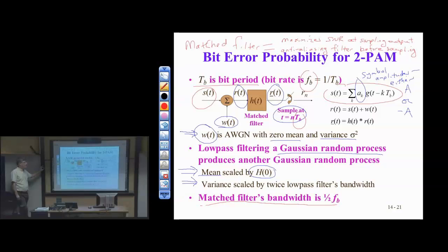Whenever I demodulate, I need to modulate followed by a low-pass filter. So the matched filter becomes a demodulating filter. So you have one filter playing three roles. Why have three different low-pass filters in cascade? That's kind of silly. Are you talking about moving the bandpass down? Yeah, the conversion from bandpass to baseband through down conversion. The matched filter would be the demodulating filter in that case. That's three roles to play. Same one filter doing three different tasks.